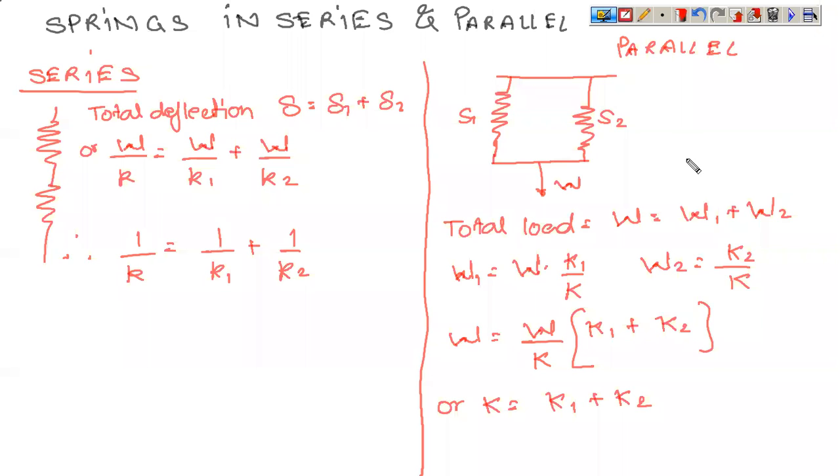The only addition that we have in open coiled helical spring is you need to find out both J and I. J is pi by 32 d to the power 4, I is pi by 64 d to the power 4. Other than that, everything is a given data. You just need to put down the values and calculate whatever is unknown. Now, one topic that was left yesterday is whether it is an open coiled or a closed coil helical spring.